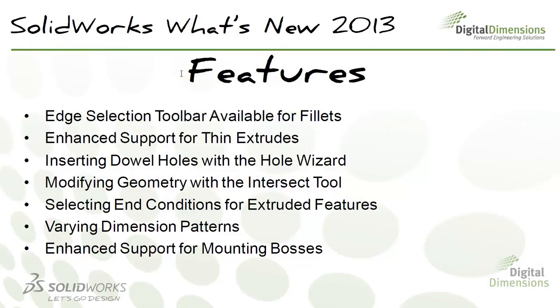And now this is going to be one of my favorite new features here, the intersect tool. So I'm going to show you 3 different examples of this one. The intersect tool, it's nice because you can throw the kitchen sink at it. It works with solids, surfaces, and planes. So solid body, surface body, and planes. You can have it consume surfaces so you don't have to delete the body, so that saves some time.